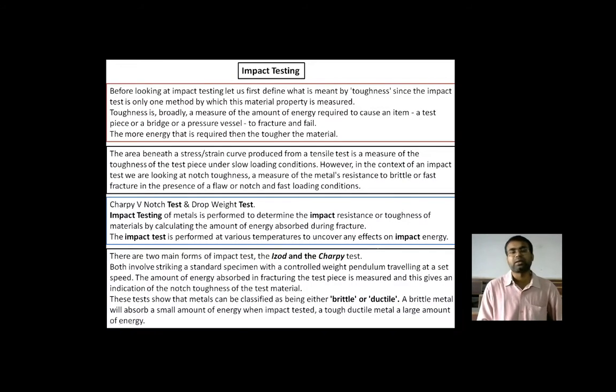It means it breaks down at that point due to the brittle nature. Why? Because the microstructure of that particular material possesses a very hard structure that is called martensite. And that martensite is hard in nature but brittle in nature also.